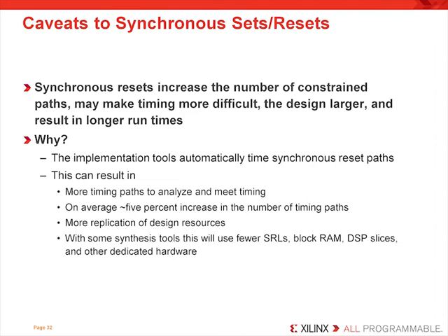As an FYI, there have been cases where other synthesis tools will simplify the synthesis result so that it does not take as much advantage of the dedicated hardware when it determines that a design will be harder to meet timing. So it will basically infer very few shift register LUTs or block RAMs. So the design gets built out of additional LUTs and flip-flops to try and get as lean as possible, which can make it harder to meet timing. In this case, make sure your synthesis tool is inferring the appropriate resource, and if it isn't, instantiate the appropriate core into your design.